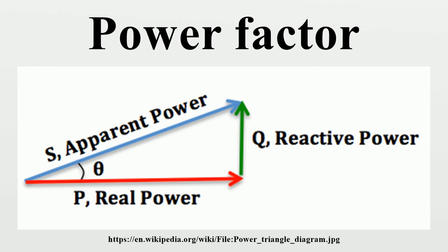If theta is the phase angle between the current and voltage, then the power factor is equal to the cosine of the angle. Since the units are consistent, the power factor is by definition a dimensionless number between -1 and 1. When power factor is equal to 0, the energy flow is entirely reactive and stored energy in the load returns to the source on each cycle. When the power factor is 1, all the energy supplied by the source is consumed by the load.